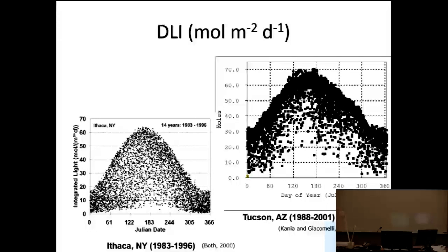Yeah, because in practice, it's from April to August, maybe October, you have a shade cloth. In the greenhouse, if you're not familiar, you have a movable shade cloth, and the typical practice is that whenever outside radiation exceeds the set point, 1,000 micromoles or 400 watts per square meter, either unit, they put the shade.